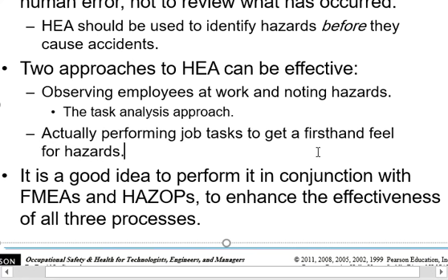If I'm doing the job, I can tell, hey, oh, we have lots of noise. Oh, this robot is very close to my finger, to my body. Or I need taller fences. I need to install a safety light curtain. I need to have a safety mat. I need to have an e-stop. So all this, I can do from the first job.